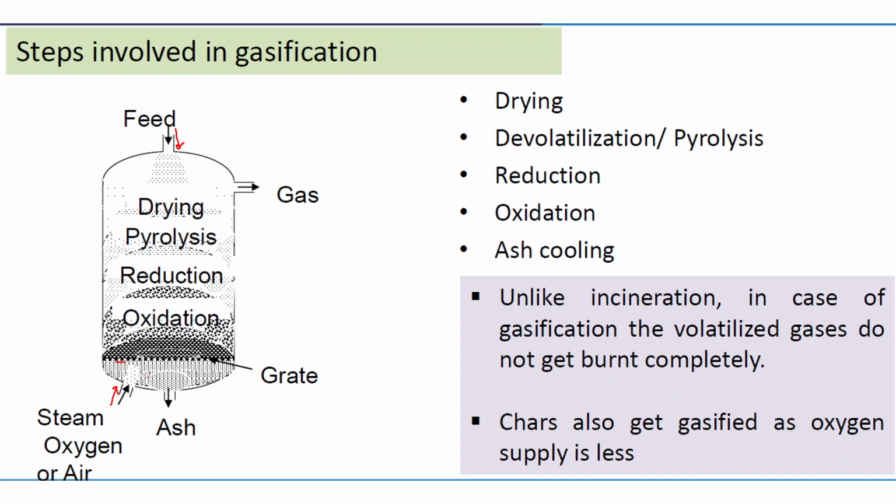As we go up, the oxygen content starts to decrease. Pyrolysis takes place in the absence of oxygen or in the least amount of oxygen. As we go up, the oxygen amount decreases and pyrolysis takes place, and in the upper zone only drying takes place, that is the drying of volatiles and moisture content, if any is present.